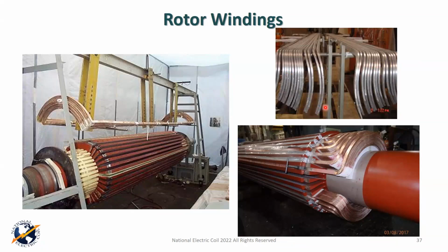You have zero margin. That butt braze has to be just right. The process is extremely important. The tooling to make it happen is important. And the qualification of the brazers, who not only understand and can execute that process but consistently do it, is really important with those designs.